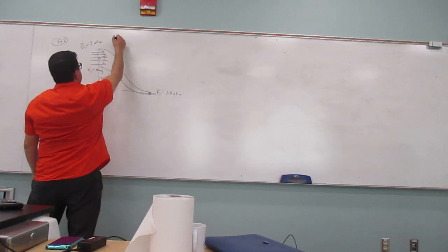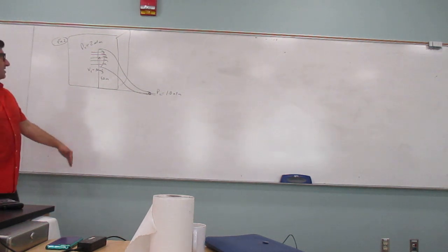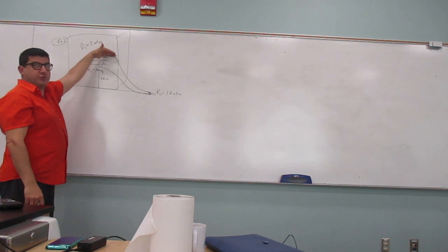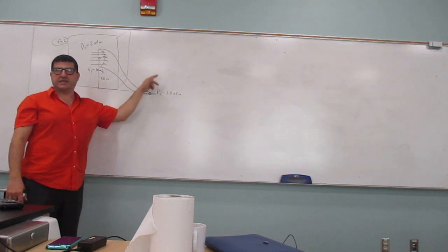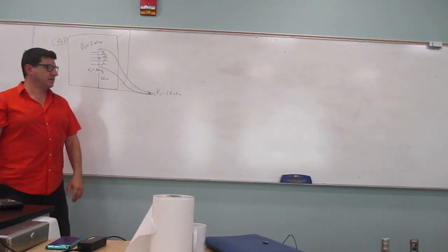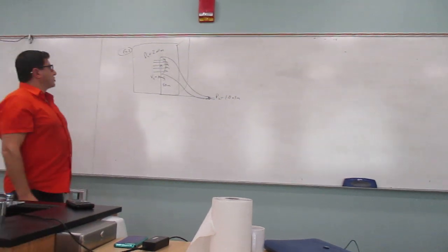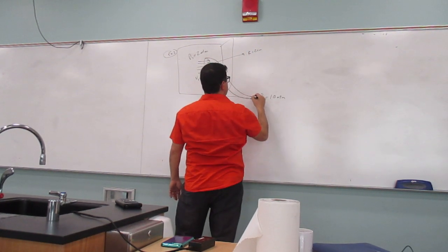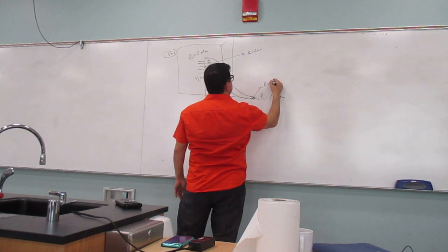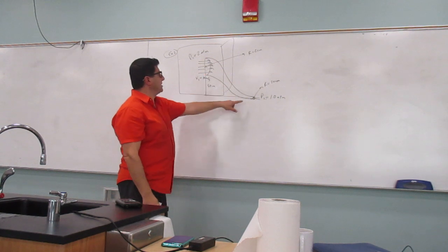You can imagine this is a building, a power manufacturing company or something. The machine is pushing it at 2 atmospheres, but this end is open to the atmosphere. It could be a river, and it's dumping the water to the river. So the pressure here is 1 atmosphere. Now let's say the radius of this is 2 meters, and the radius here is 20 centimeters. So it's very constricted. Tell me, if V1 is 10 meters per second, what's V2 going to be?